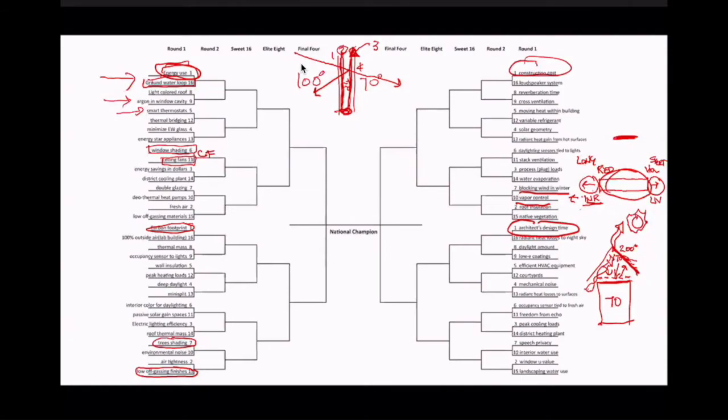Maybe. But it depends how thermally coupled it is to the building. You can imagine a building here, and if you think of your roof element as a giant shading element that's somehow theoretically suspended 8 inches above the roof, you can understand how even if it absorbs heat, it really is preventing radiant heat from getting to the building below. So it's reflecting the solar energy. I'm not sure, depending on what kind of roof you have, that when you're thinking of grass, it really is thermally coupled to the roof.